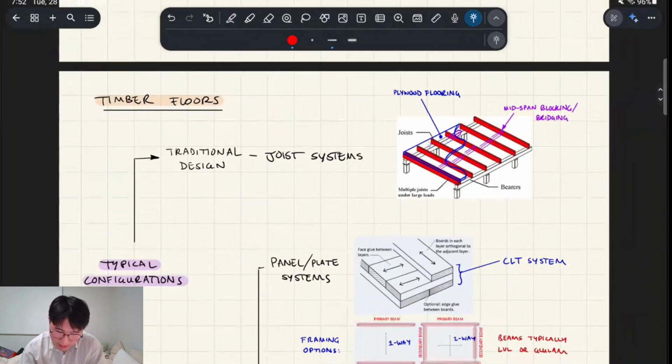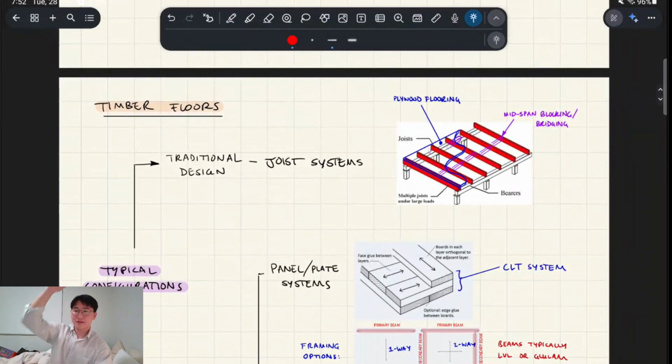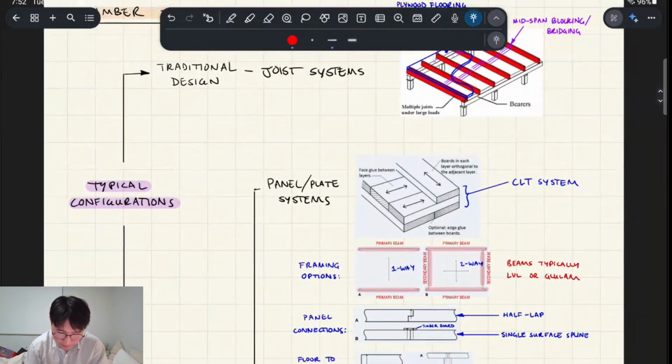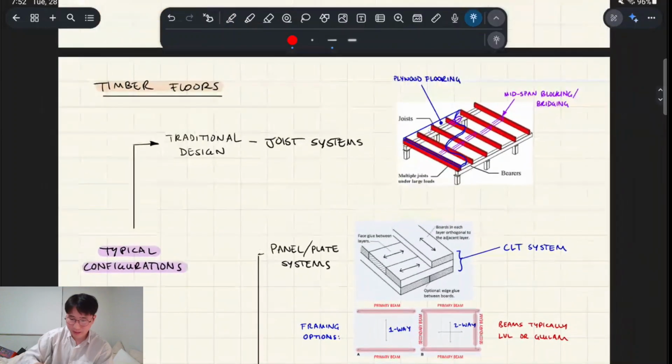And it's basically the same as if you've seen the stud walls. You've got your vertical stud members, and you've got the noggins, which are running horizontal, which restrain it from compressive buckling. Similar idea, but now we flip the whole thing on its side. And instead of compression, the joists are taking